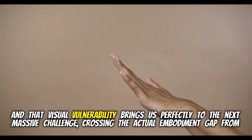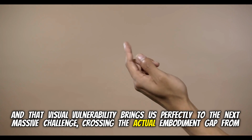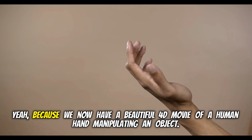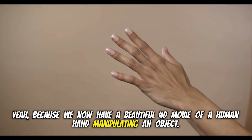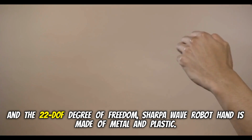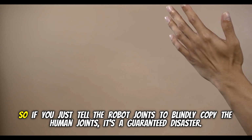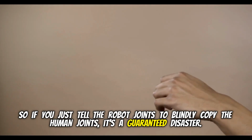And that visual vulnerability brings us perfectly to the next massive challenge, crossing the actual embodiment gap from human anatomy to robot hardware. Yeah, because we now have a beautiful 4D movie of a human hand manipulating an object. But a human hand has soft tissue, specific joint lengths, and unique kinematic constraints. And the 22 degree of freedom Sharpa Wave robot hand is made of metal and plastic. It has vastly different geometry. So if you just tell the robot joints to blindly copy the human joints, it's a guaranteed disaster.